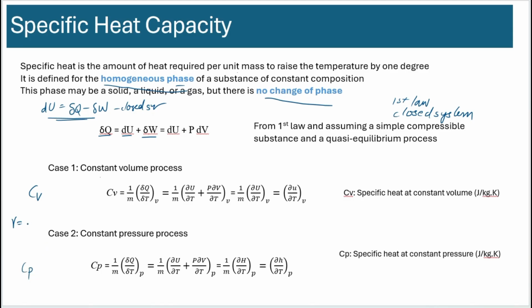If you remember the gamma value, which is the ratio of specific heats, it is the ratio of Cp over Cv. Cp is typically greater than Cv, and you will know why really soon. The ratio is usually bigger than 1. Now, what exactly is Cv? It's the change in energy needed to raise the temperature by a small amount at constant volume. Because it's specific heat, you have to include a 1 over mass term. Specific heat is the energy change per temperature change at constant volume.